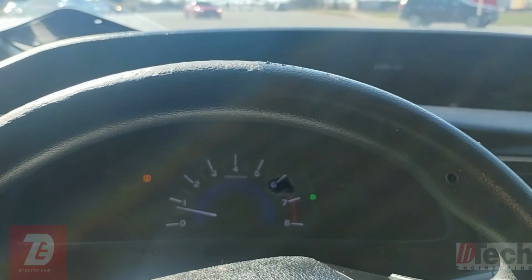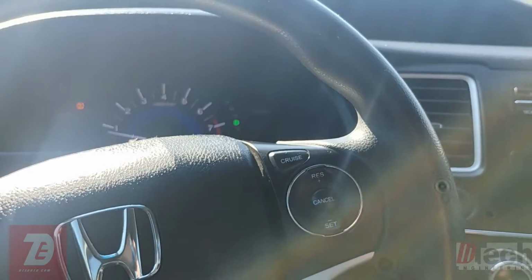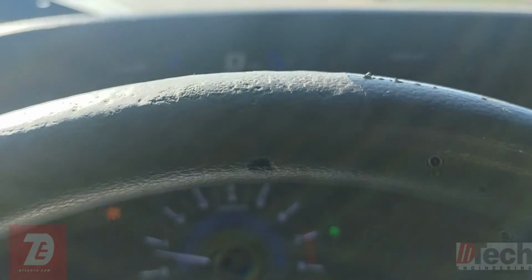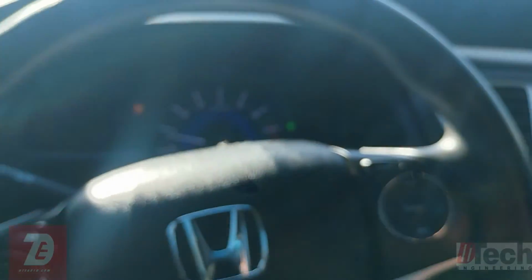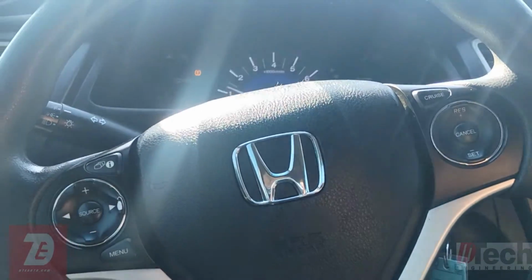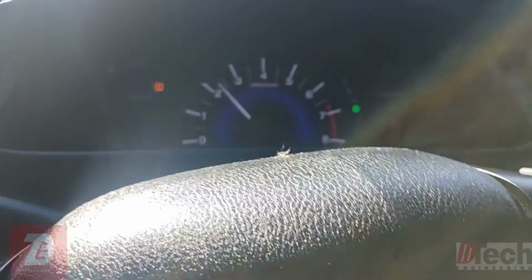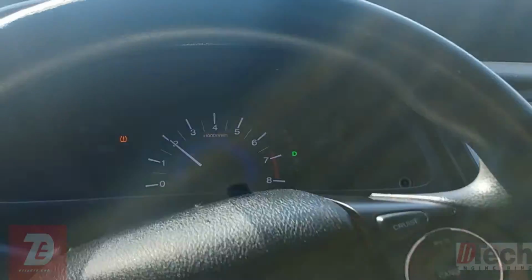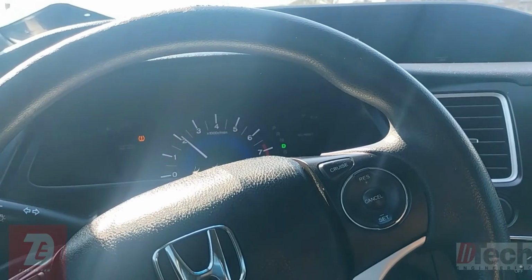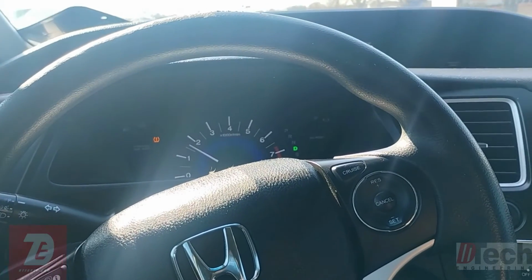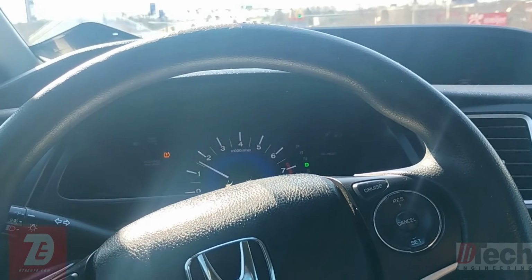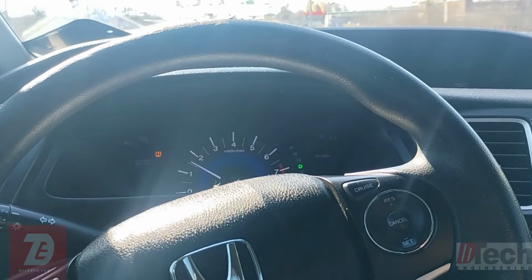Alright guys, so I just wanted to get a conclusion on this. I wanted to show you no more lights. I know it's hard to tell the glare, but wheel speed sensors, everything is working fine. No check engine. There was a fuse 15 was blown. That affected the O2 sensor code and the evap code.